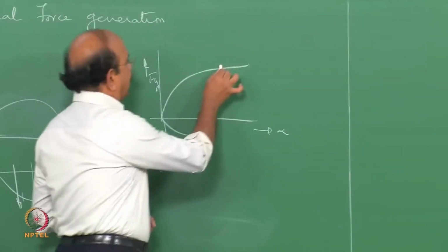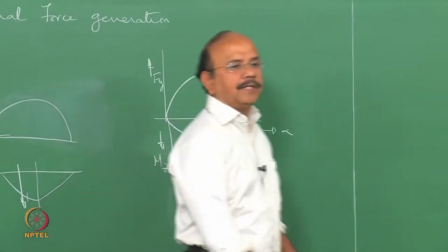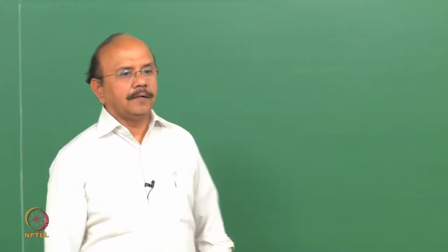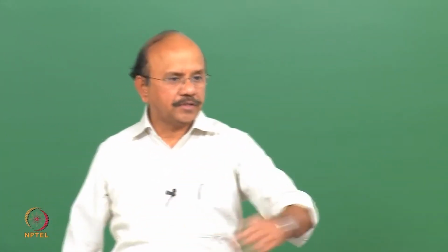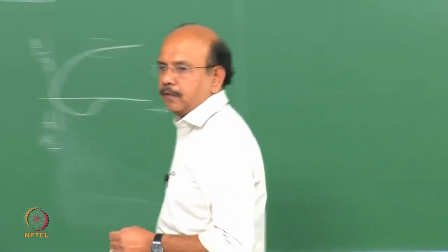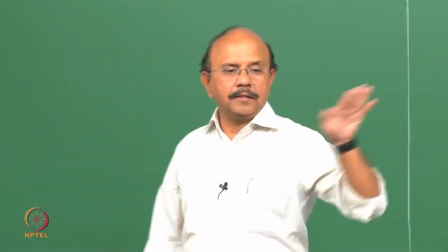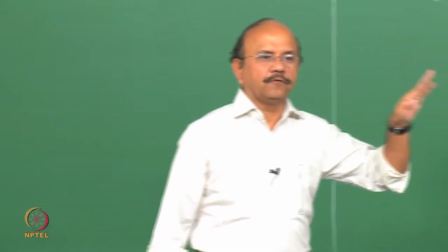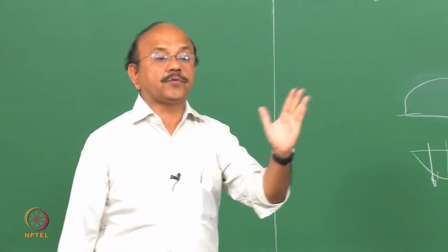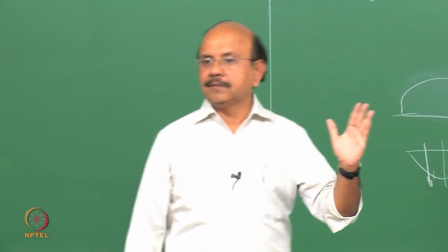So when all of them have reached mu Qz, the maximum force that can be delivered by these bristles, the resultant force position now shifts towards the center and t goes to 0.